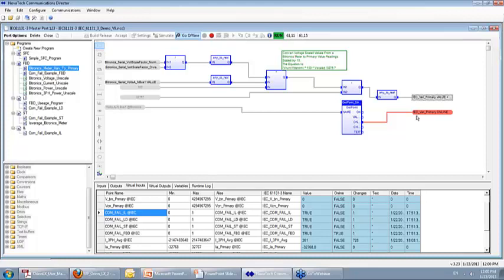I also have created within this routine a get point instruction so that in case the meter is not communicating, I can affix an online attribute which would alert SCADA that this derived value, or this unscaled primary value, is either being updated online or offline, that communications have ceased.